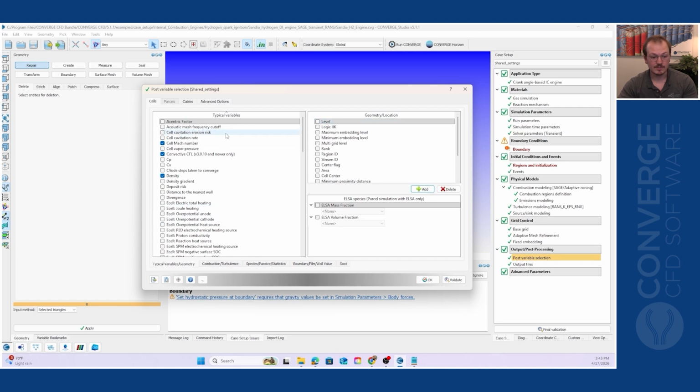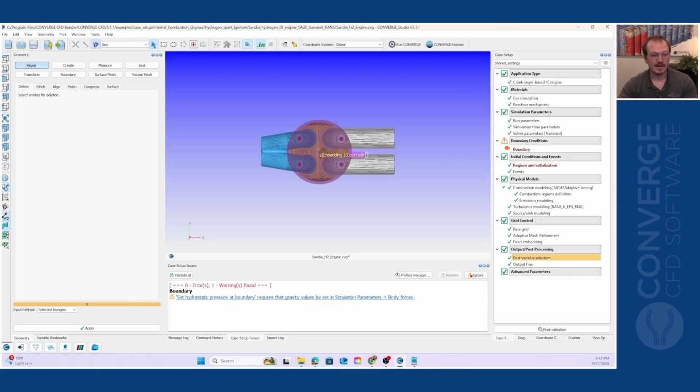Additionally, for multi-stream simulations, you can combine the data for all streams into a single set of post files, write a separate set of post files for each stream, or write separate sets of post files for steady state and transient streams. That covers the output files CONVERGE creates. Next, we'll move on to discussing restart and map files, which help you initialize your next simulation.